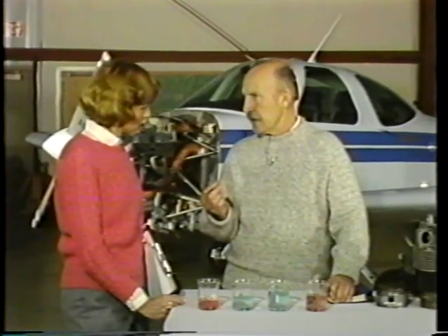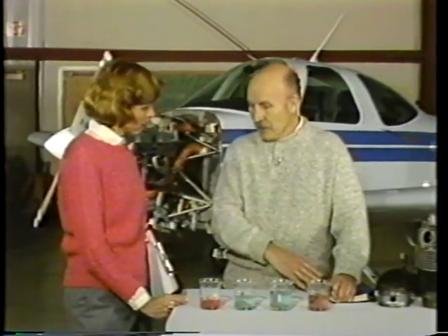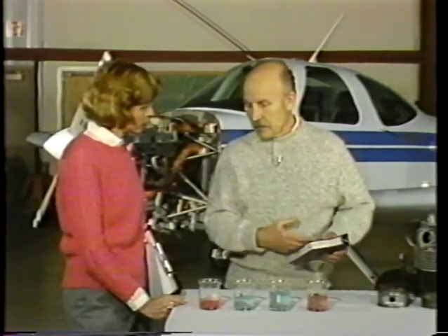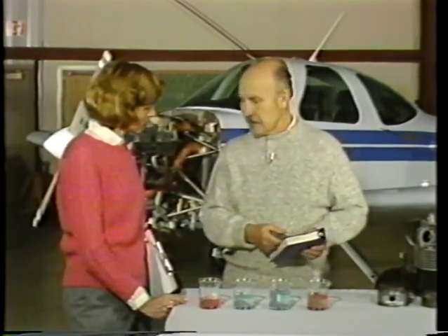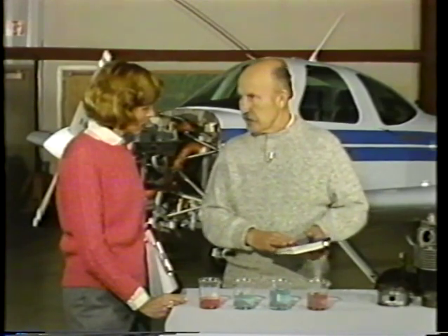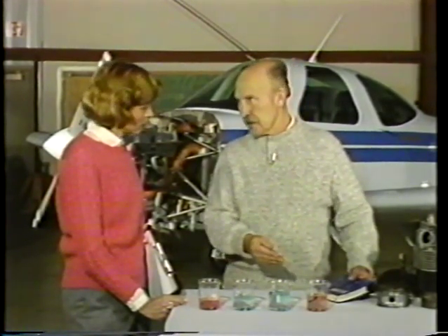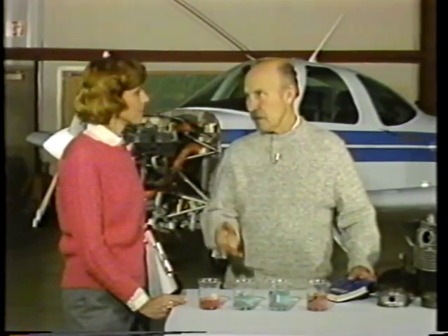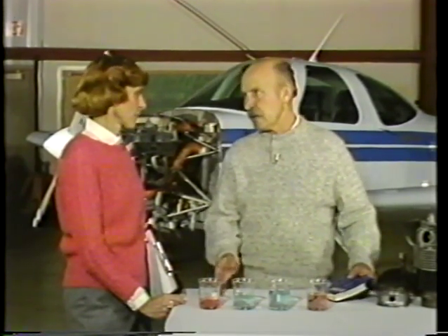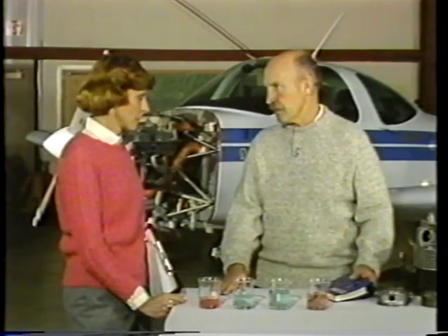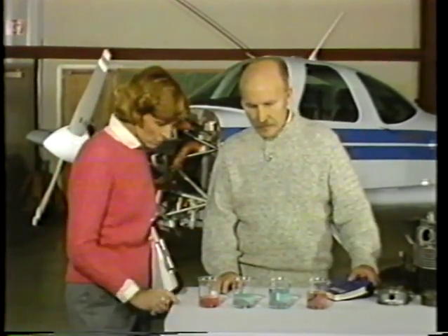then you know it's been contaminated. And again, by referring to the manual on the airplane, you will know if this is acceptable or not. On the Skipper, for instance, it requires 100 octane, so if we find a fuel sample that's clear, then we know it's been contaminated with a lower grade fuel, and we shouldn't fly the airplane till this has been corrected. It takes a little while for that color to change, doesn't it?